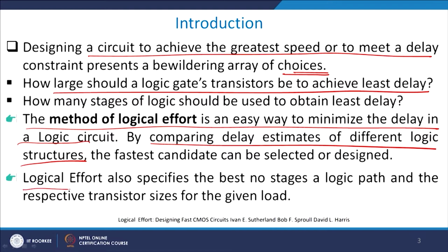Logical effort also specifies the best number of stages in a logical path and the respective transistor sizes for a given load. Which means that if I know for sure that my output load is CL, or a load is given to me, then can we do a back calculation and say that okay, my transistor size should be this much for this much load to be driven by an input to get the minimum delay, right.